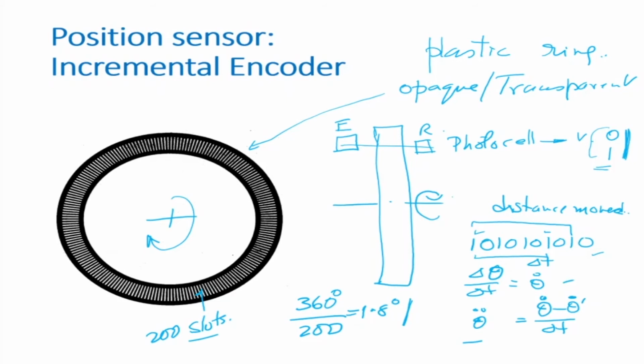Any position measuring device, not only in robotics, in NC machines, in aircrafts, anywhere where you're measuring position, at the back of the motor there will be an encoder. And the basic structure is like this. So there is a motor here, motor shaft will have this encoder here. 2 or 3 encoders in parallel. There is a gear in front. Okay, that is the construction of industrial motors that are used for robotics also.